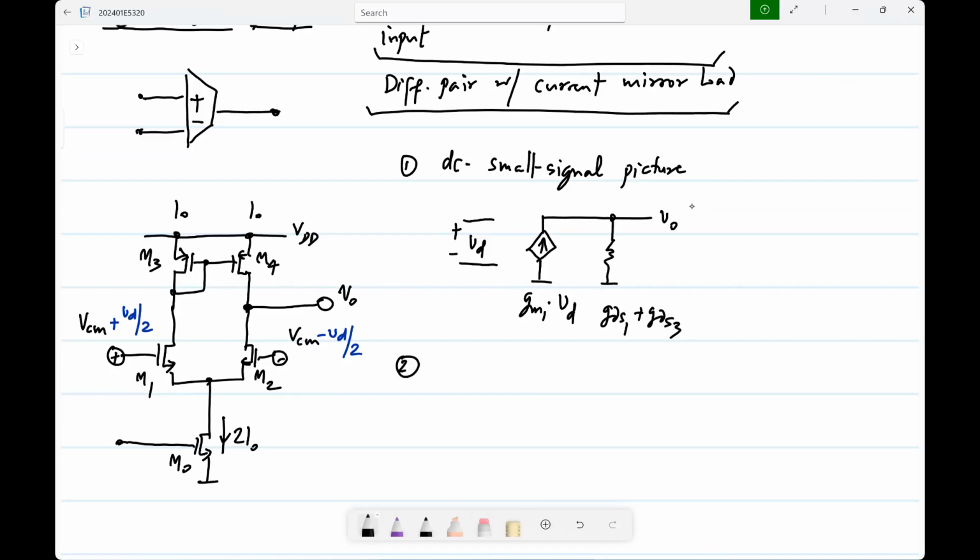And large signal wise, you have to specify the swing limits. Essentially this op-amp has 2 inputs and 1 output, so you have 2 different swing limits. What I mean is that this is the common reference node and you have 2 inputs VIP and VIM and 1 output. So anytime you have that, of course you have 2 different transfer functions, 2 different inputs, right? VIP and VIM. But functionally it doesn't make sense to treat VIP and VIM separately. We still have to have 2 inputs.